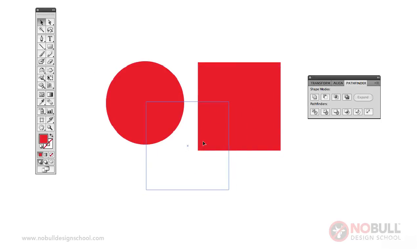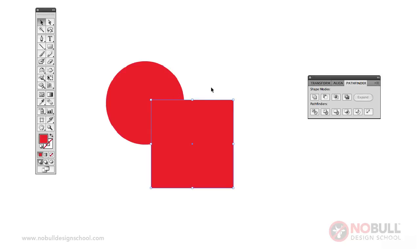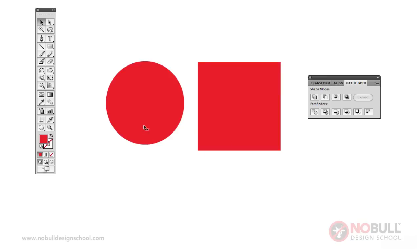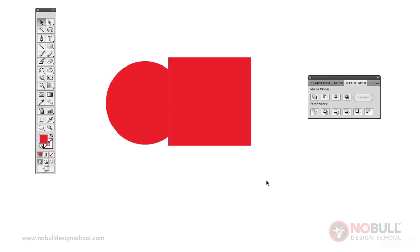Okay, so let's put that over top of here again. Imagine I wanted that square removing, so I wanted to minus the front from the back. So let's go minus front. As you can see, the square has now been extracted from the circle. See what else we can do. Let's put the two together again, and I can merge them. So now that's one object.